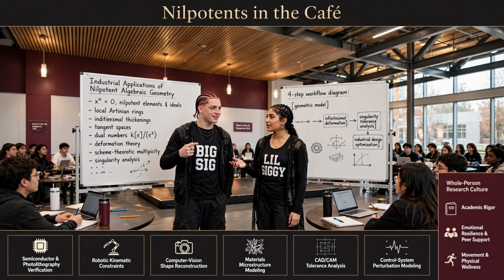Okay, imagine you are parallel parking. You cut the steering wheel hard right and back up a few feet. That vector is f1. Right. Then you cut the wheel hard left and pull forward a few feet. That vector is f2. You alternate right back, left forward, right back, left forward. And none of those 4 individual movements slide the car directly sideways. No. But the combination of those movements, the Lie bracket of the alternating vector fields, generates net motion in a completely new direction that was previously blocked by the non-holonomic constraint. The Lie bracket mathematically spans the tangent space, allowing you to slide sideways into the parking spot.